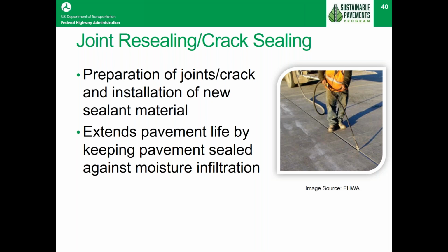The materials here, again, are typically hot asphalt materials or could be a cold applied silicone material. Sometimes in concrete pavements, they do use preformed compressed rubber that's used in joint seals. The most important thing here, like it is with asphalt, is that the joint needs to be cleaned before it's sealed. So you'll see the guys using air to clean things out and get the stones and other incompressible material out of there that will damage the pavements as they tend to contract and expand.